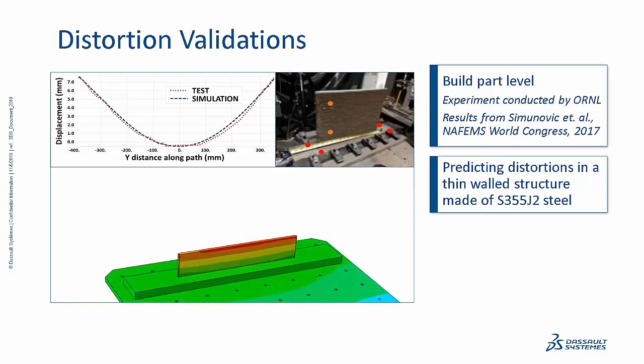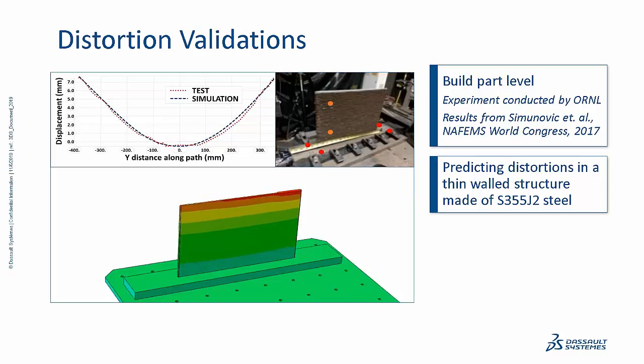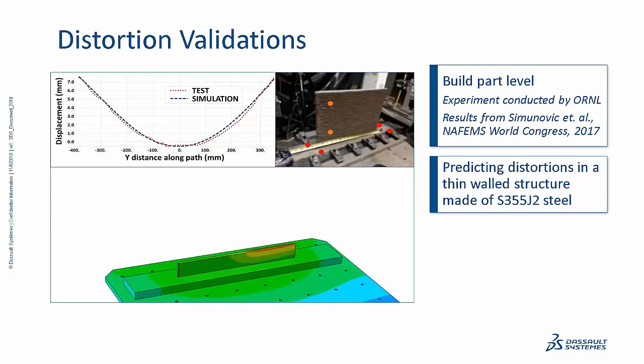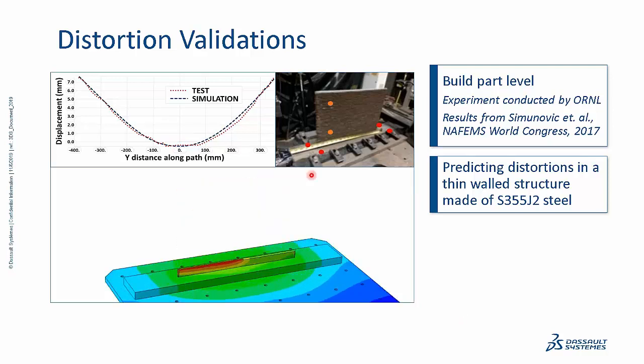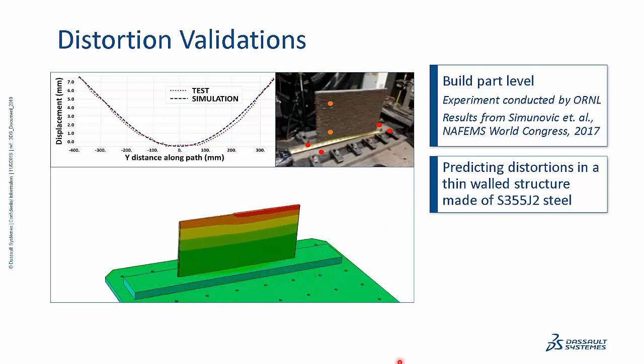This is an LDED, direct energy process validation. It's a joint work with Oak Ridge National Lab. At Oak Ridge National Lab, they use the MBAAM, or we call it the metal big area additive manufacturing. They use this robotic station comprised of a robotic arm with controller, welder, and wire feeder. A mild steel material was used to print this thin wall structure. It's about 30 centimeters high. It's on top of this build plate, which was clamped to a positioner table.